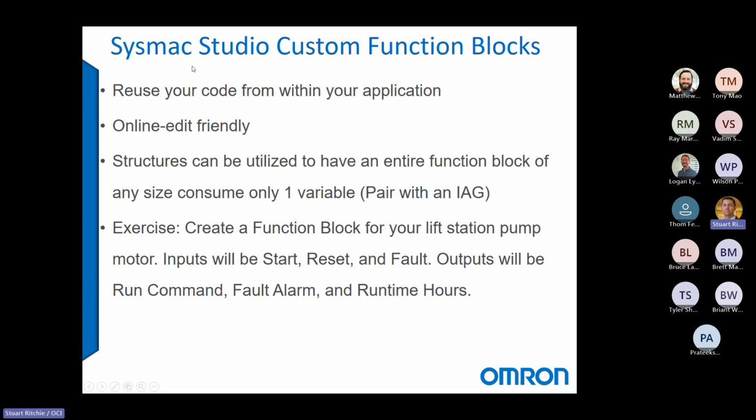Okay, custom function blocks. So if you're familiar with other platforms, these are sometimes called AOIs. They're fairly similar to a subroutine in a text-based programming language. But essentially, when we make a custom function block, it lets us create some code and then reuse it indefinitely to have identical duplicate instances of this code running in your PLC.